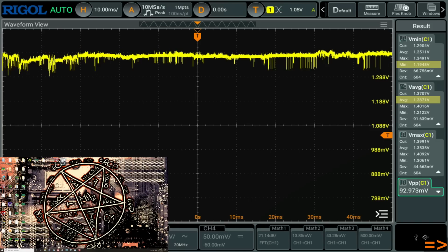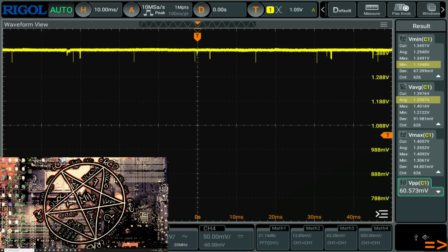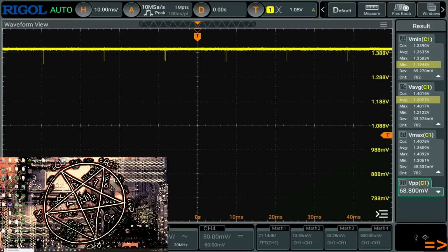Yeah, so I guess if you have this board, or other boards from MSI that have this feature, the way to go about overclocking with them would be to use mode 8 LLC, and then just fiddle with the saturation current to get the desired behavior.